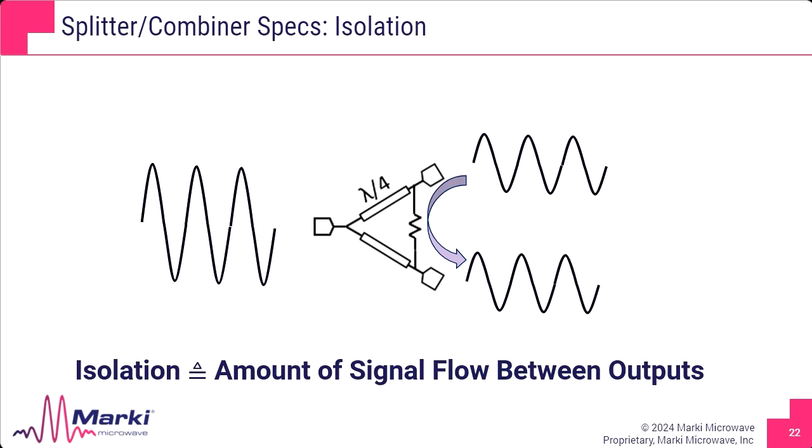So if we take, for example, a perfectly in phase signal at the two ports on the right, the instantaneous voltage across that resistor is 0. So no current flows and all the signals combine to the output. Now, as you move these signals out of phase, that resistor begins to eat up some of the signal, rejecting off-angle signals. And this directly impacts the directionality of your beam, especially in a receiver scenario.